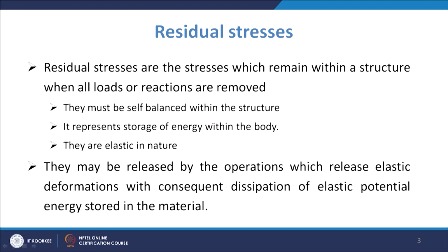So, when by some means you try to remove these stresses, the body goes to a different state. Suppose you subject the specimen to some heat treatment, say annealing. It will come to a different equilibrium state, and a new static equilibrium will be restored when you remove those external means.